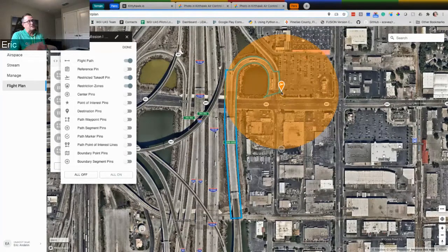So in this case, they're going to take off, get that IMU active up here somewhere. We don't want them going over here with the IMU and then starting the mission, because if they do that, no mission will start. So we want to give them a big area to work with. They're going to shake up the IMU right in here. Then they're going to execute the mission.